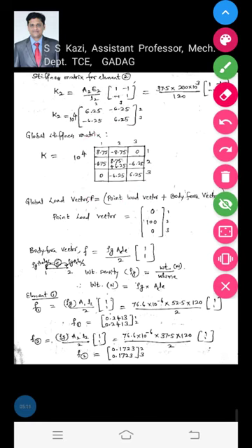Generate a grid like this, write the K1 terms into the 1 2, 1 2 boxes, and the K2 terms into the 2 3, 2 3 boxes. One common term you will get in both matrices, that is the 2 2 term, with 8.75 and 6.25.